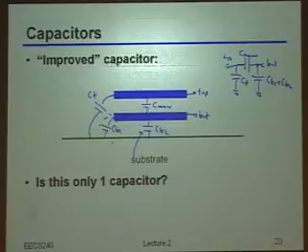Okay? So because of that, people often refer to these basically fixed parasitics that are connected to the substrate that you can't really control as a so-called bottom plate parasitic. It turns out in reality, oftentimes there's no difference between the so-called top plate and the bottom plate. It's just that because they sort of have this picture in the back of their minds, the term bottom plate really caught on, and so if you hear that, you should always think that there's actually parasitics on both sides of the capacitor, but sometimes indeed the bottom side is worse than the top side. Okay?